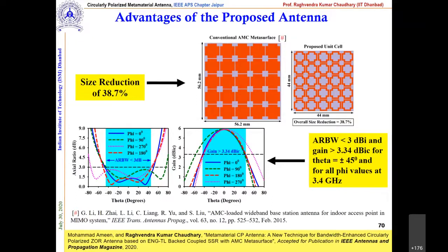And this plus minus 45 degree, I would suggest to the audience, please check the antenna, because sometimes we make the antennas and get the peak gain and say that this is the antenna. Not actually. You have to check whether you are getting sufficient beamwidth, sufficient gain, and what the compactness is.